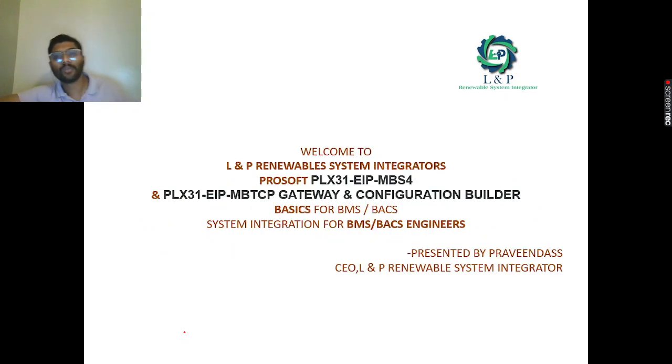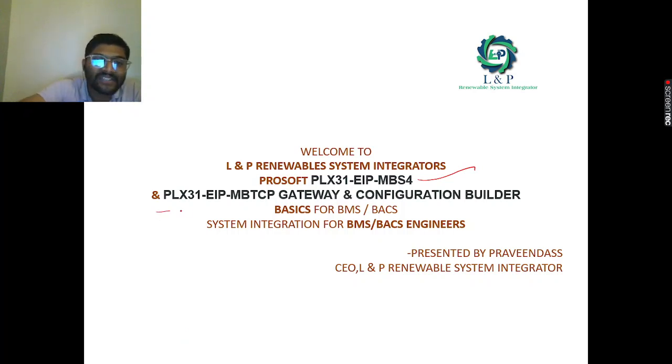So welcome to Prosoft Configurator. Today we're going to see, using Prosoft Configuration Builder, how to configure PLX31 MBS4 gateway and PLX31 MBTCP gateway modules.